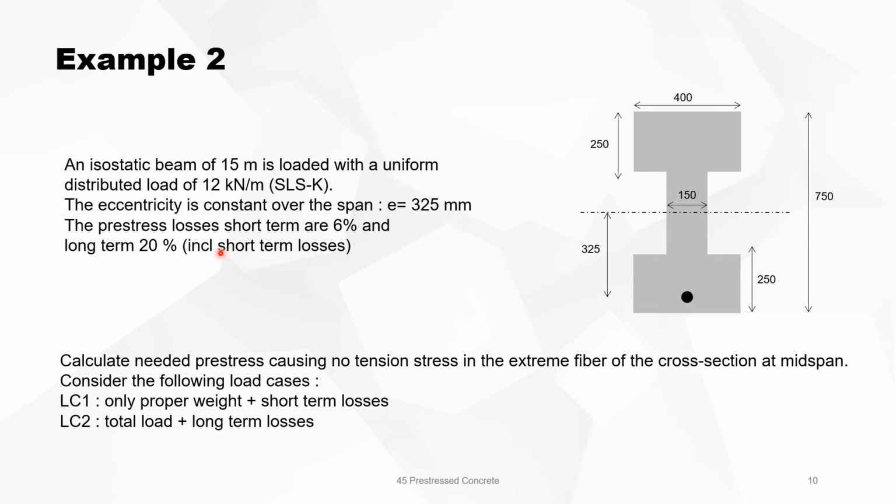now the pre-stress is not given. We have to design the pre-stress in such a way that for the cross-section at mid-span, there is no tension stress in the extreme fiber. And we will consider two load cases, again, short-term and long-term.